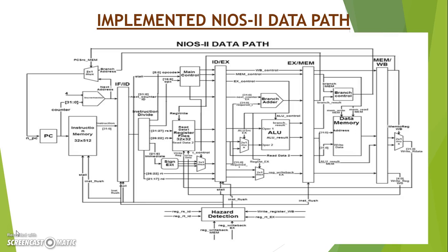The fourth stage is the data memory stage. The read and write operations related to memory are controlled by the read mem and write mem signals. The address from where data is to be read is given by the ALU, whereas the data to be written is provided by the previous stage read data 2. The last stage is the write back stage. This stage is the smallest one, which gives the address of the register where data is to be written in case of an R-type operation.